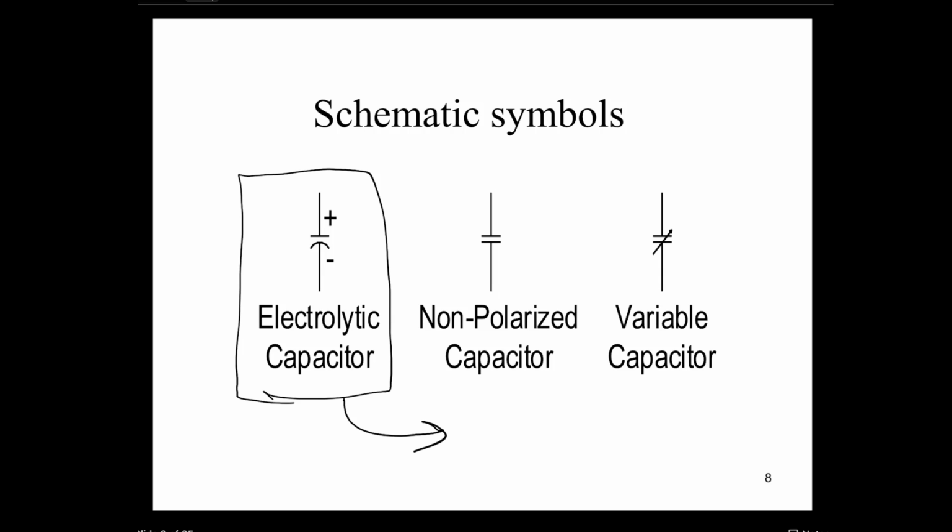I think it would be logical, and you'd be right to say that if that's the case, these electrolytic capacitors are only used in DC circuits. And just a little bit of a story there. Electrolytic capacitors are used to do that filtering I talked about in that power supply. And if you are building that power supply and you connect the electrolytic capacitor onto the AC side of the rectifier instead of the DC side, it explodes.